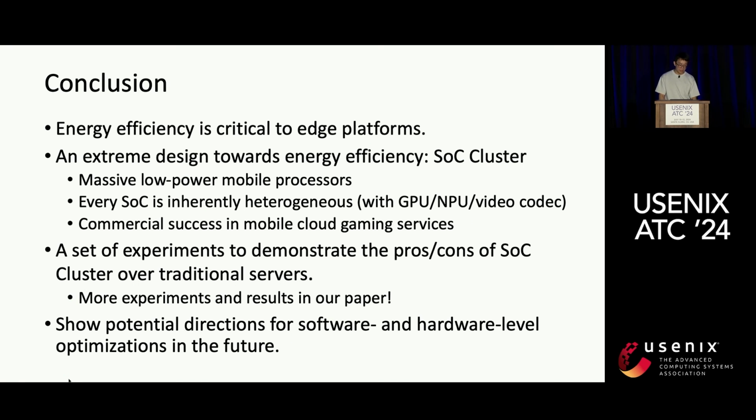So let's conclude. The first is common sense, the energy efficiency is critical to the edge platforms. So in our work, we propose an extreme design towards the energy efficiency SoC cluster. Each SoC cluster consists of multiple low-power mobile processors, and each SoC is inherently heterogeneous with CPU, GPU, NPU, and video codecs. And such an SoC cluster is commercially successful in mobile cloud gaming services, and we want to extend it to more general workloads.